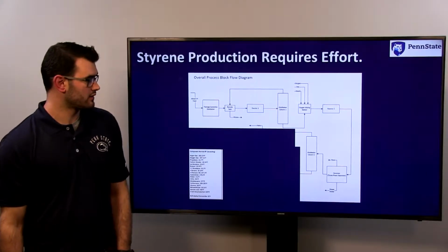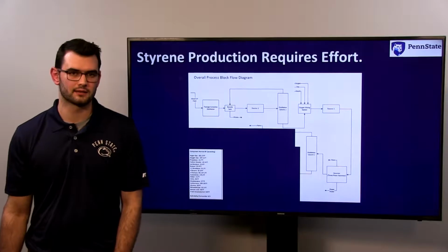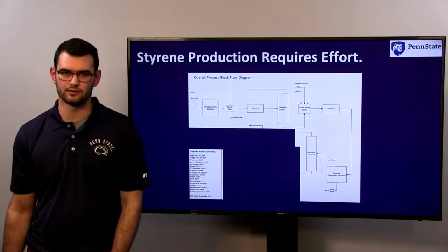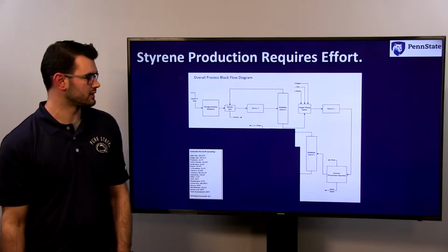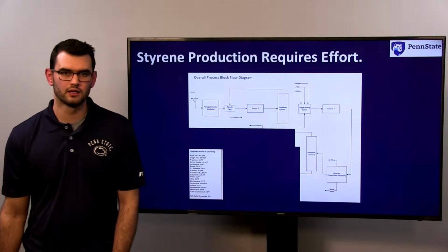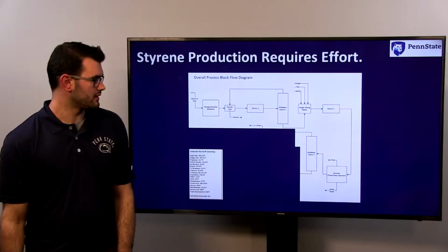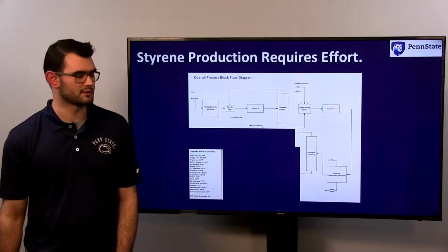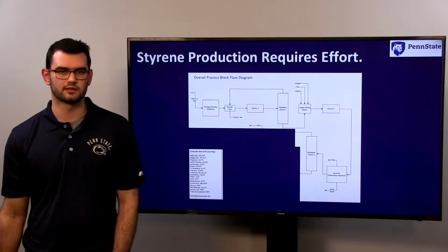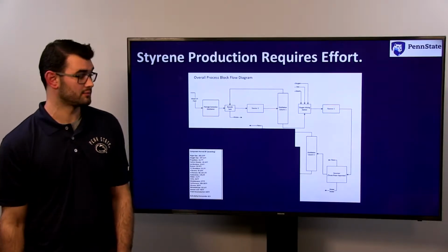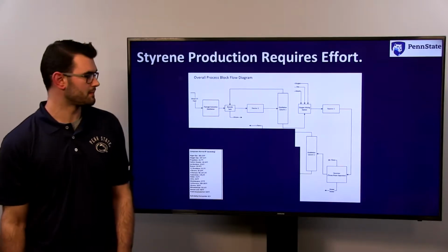And the water phase is collected out of the bottom as a 98% water composition by weight that is sent to a waste treatment facility after being treated for pH by our process. The gas phase that comes out of the top of the decanter is just sent to a flare. We found this was the easiest way to responsibly dispose of this waste stream.